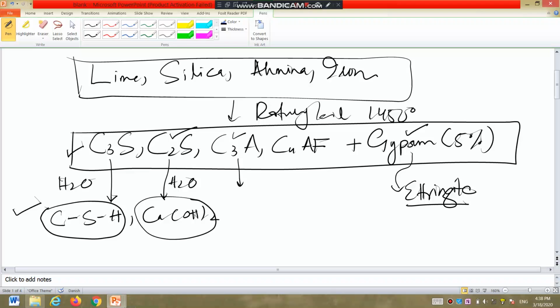Therefore, it is required that if a structure of concrete is to be built underground where the soil contains sulfate ions, or marine structures where sulfate ions are present, these chemicals like tricalcium aluminate and calcium hydroxide should be minimized in their content.